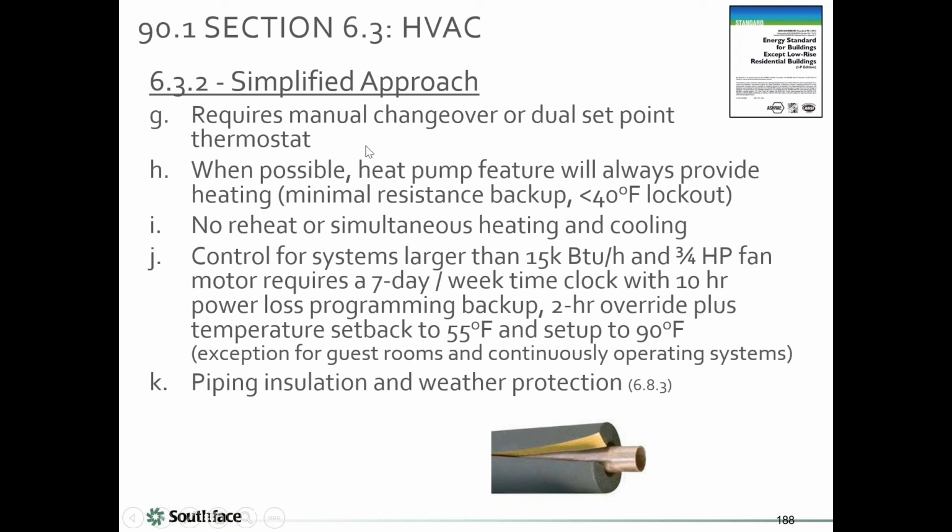Under the simple approach, we're not going to allow you to do reheat for moisture control. Reheat is where you have to sort of overcool the air in order to dry it, and then if you dumped it in, it'd be too cold, so you warm it back up again. And that, as you can imagine, is very energy intensive, particularly with electric resistance reheat.